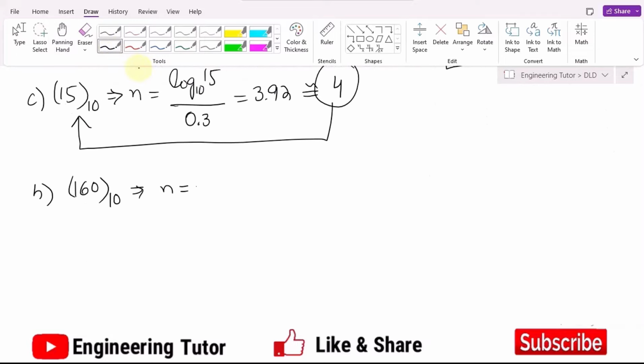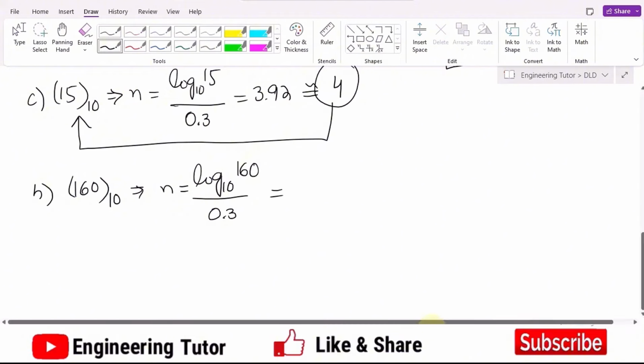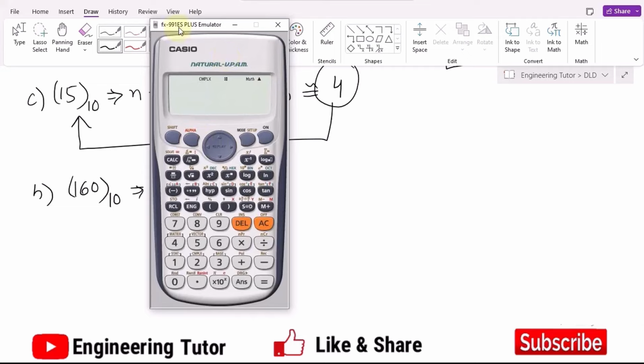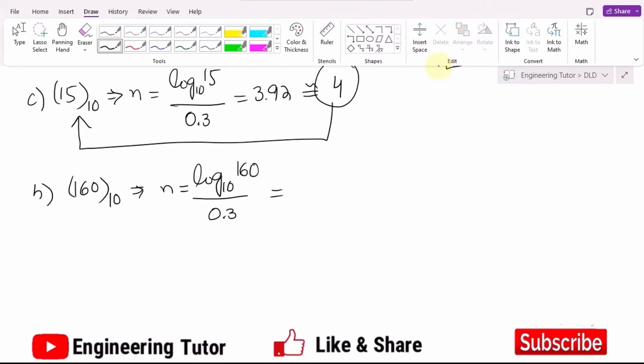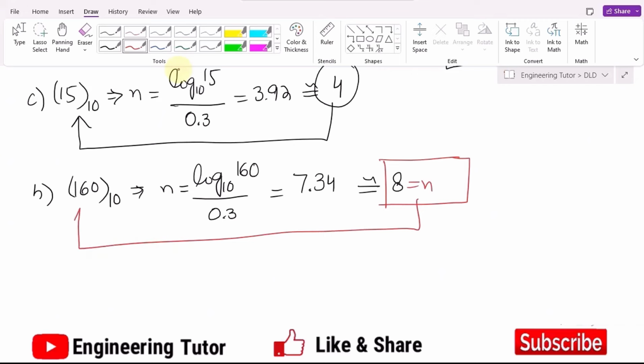Now let me use my formulation which I have made. So log of 160 divided by 0.3. How much would it be? This is 7.34. Again, rounding it off to the higher number, I will get n equal to 8. So 8 is the number of bits which can be used to represent this 160.